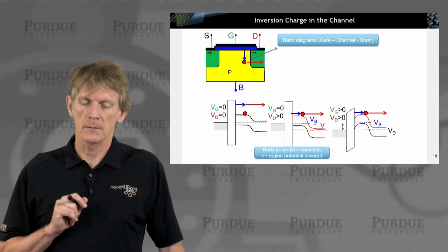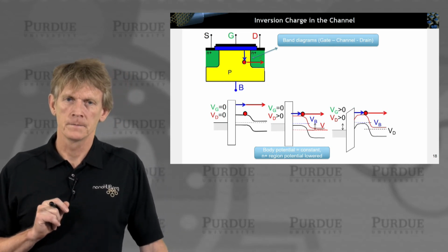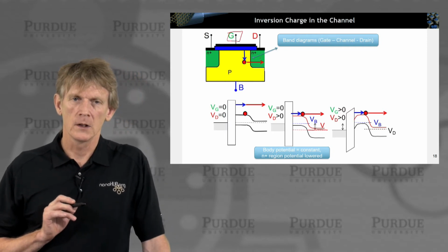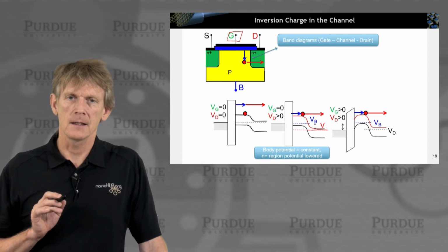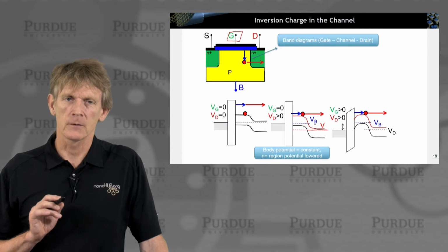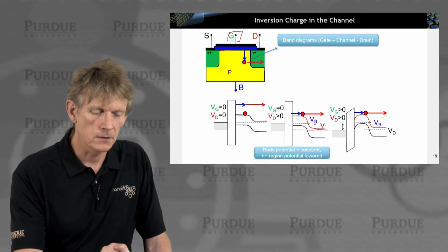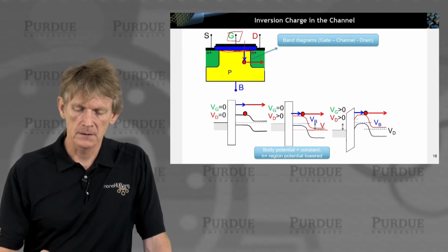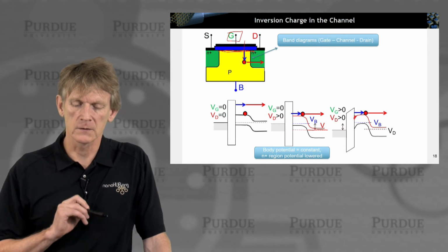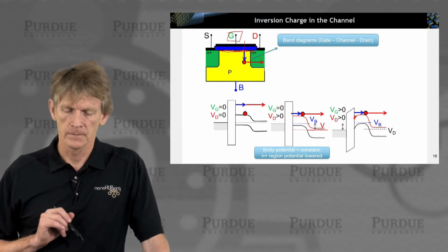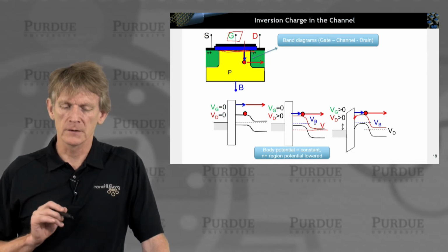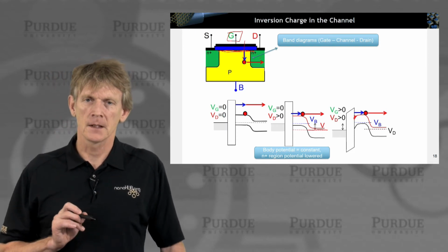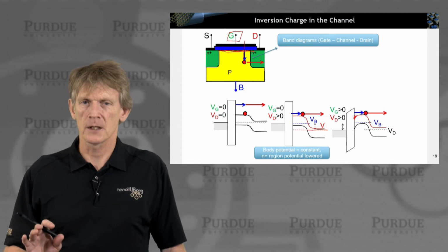Now, let's apply a gate voltage. So now we're adding a voltage here to the gate. What does that do? Well, the gate wants to create a channel, just like what we discussed right under here. It's going to create a notch of a potential in this blue direction. That's this notch. Okay, so that's where it wants to create a channel. Okay, so now we have a drain voltage applied and a gate voltage applied, and we're marching along the blue and the red vector. Okay, so you kind of get a feeling how complicated the potential will be.